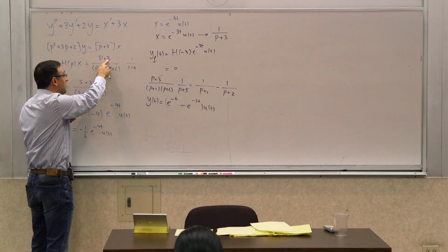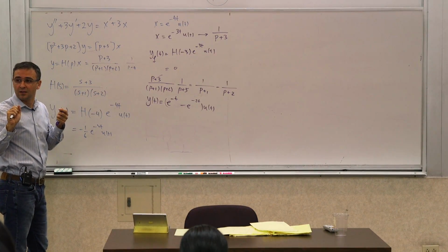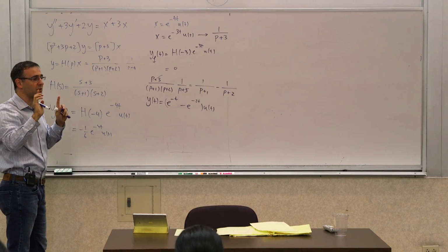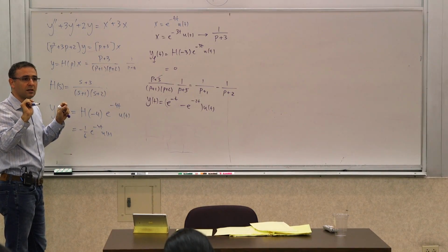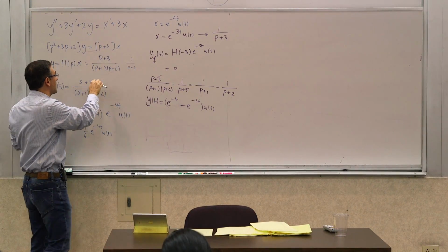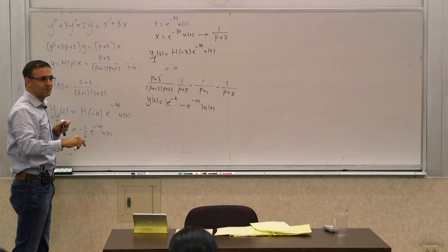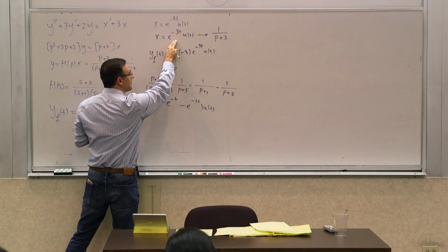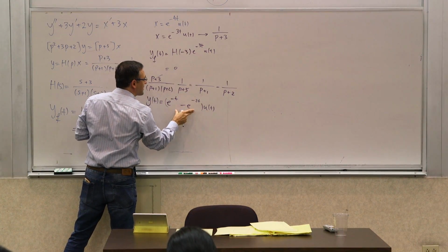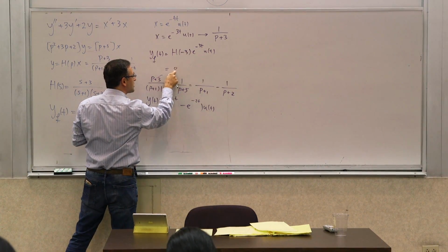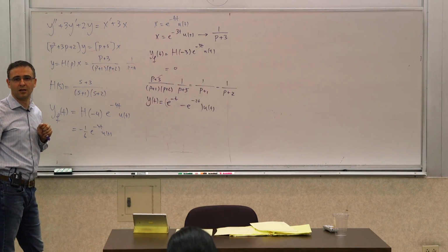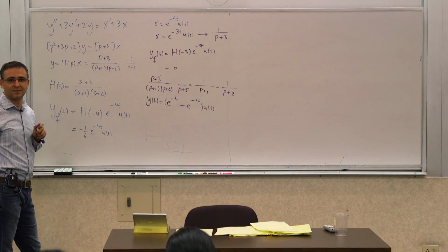It wouldn't produce the zero frequencies. Zero frequencies are not natural frequencies of the system. But it does produce the two natural frequencies plus the input frequency. This was a special frequency, the zero frequency, where it only produced the natural frequencies. It doesn't produce the forced input frequency. That's what's special about it.